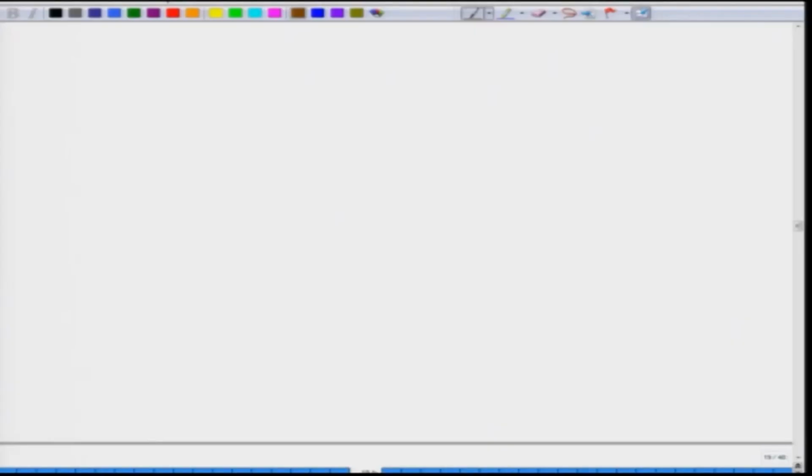So, GPS is a system through which you can figure out your location in 3 dimensions by making use of a constellation of satellites. Now, when we take any measurement, there are bound to be certain errors. Suppose you are at this location, the location is x comma y, but because there is certain error, your position is coming as x plus delta x and y plus delta y.